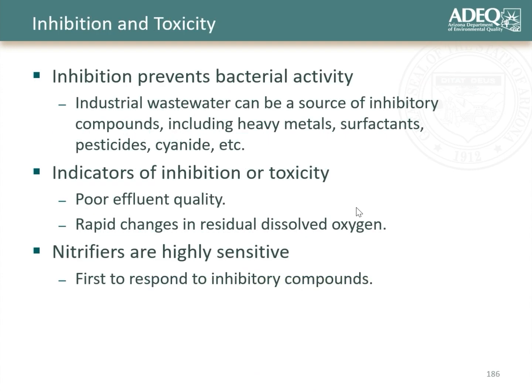So, inhibition and toxicity. As with everything, toxic compounds and inhibitory compounds can impact bacteria as well. Some of the more common sources of inhibitory compounds would be industrial wastewater, where potentially an industrial user may discharge some chemicals down the drain that they didn't realize the impact of, including things like heavy metals, surfactants, pesticides, and cyanide. These things can potentially impact your system.